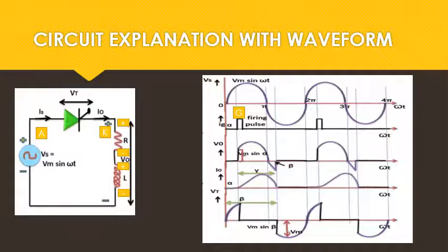We are going to give AC signal to this circuit. So that's what we see here. But we are very clear about the point that this SCR can work only for one half of the cycle, and it is going to be switched off for the next half of the cycle. So that's why we are giving a symbol like this for understanding.